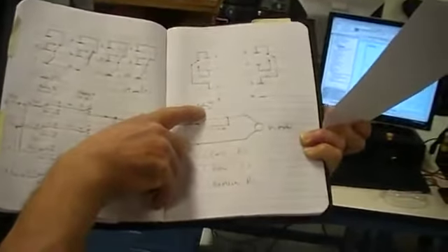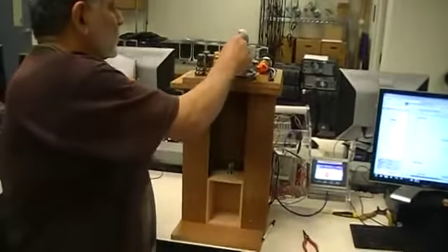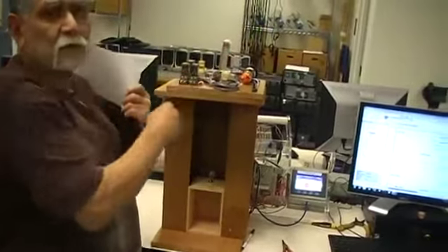Two poles have power for forward, but if you energize the relay, it takes the power from those poles and brings them down to reverse, and then the reverse circuit is wired. So you can never cross the power when you reverse polarities. You have a relay to enable the forward, and then a relay to enable the slow and high speed, depending on which resistor you're using for the motor.